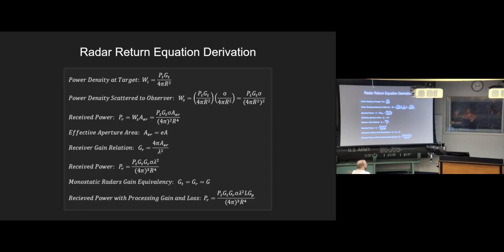And this, as you can see, is Wi here times this factor, which is actually 4 pi r squared again. This little symbol right here is sigma, but it's actually RCS. So that sigma just stands for your radar cross-section, which is in meters squared. Nothing too complicated yet. Which results in your power transmitted times the multiplication factor times the square area in meters with this factor down here, 4 pi r squared, whole thing squared.